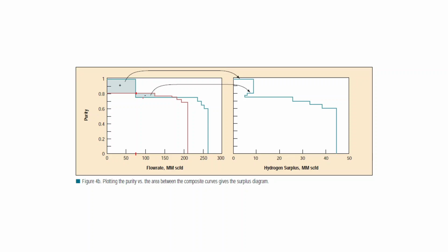And then this area, for this flow rate, we require a lot of pure hydrogen. Because this is the demand, right? The red is the demand. So this demand stream requires 80% hydrogen purity, while the stream that we have over here is 75%, for example. So that's the minus. When it goes to the minus, it goes to the left like this.